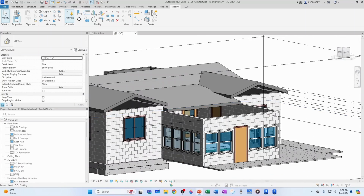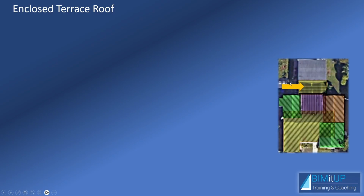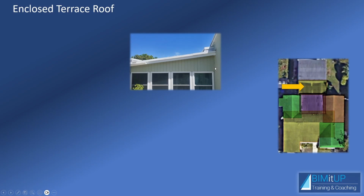So now let's create the other roof, and that's the enclosed terrace roof, and that's this one here. You can see how it slopes down at an angle of 9.46 degrees, or 2 in 12, which is equal to 1/6.